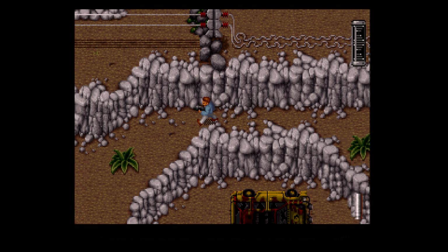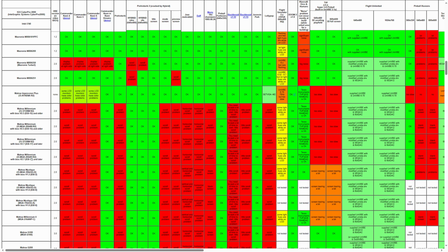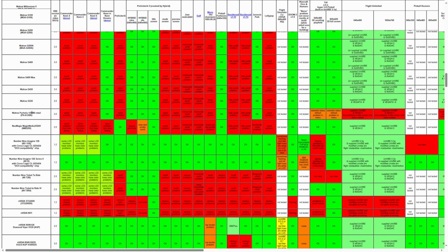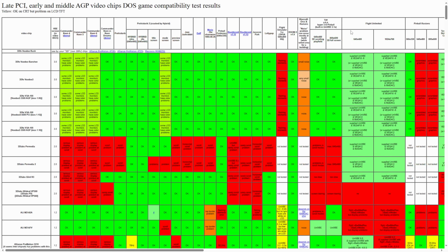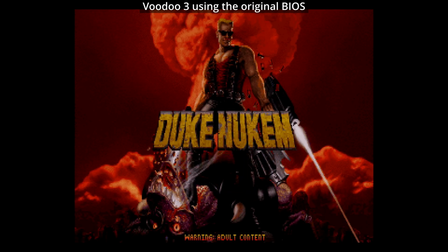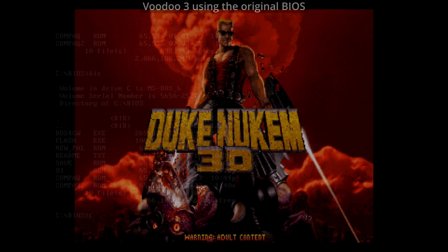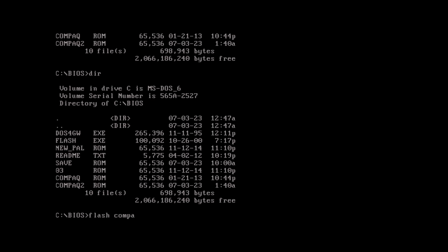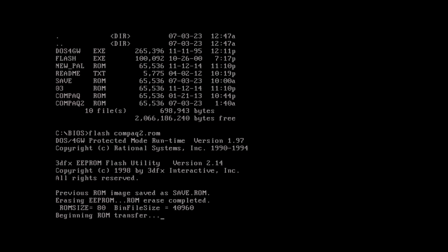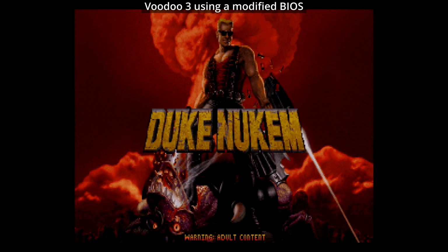And the same is true for graphics cards by Matrox. But of course, these cards can still work well for later games. And even later 3dfx cards got issues with older games. Starting with the Voodoo 3, there are artifact problems on the 320x200 resolution. However, these can be solved by a graphics card BIOS exchange. While that is not rocket science, it does require that you look into it, and ideally you also have a PCI graphics card available, which, in case something goes wrong, you can use to boot the PC to overwrite the BIOS of the Voodoo in the AGP slot.